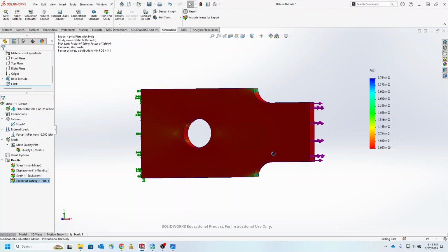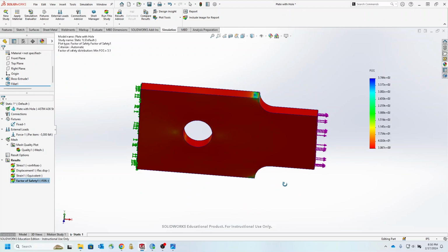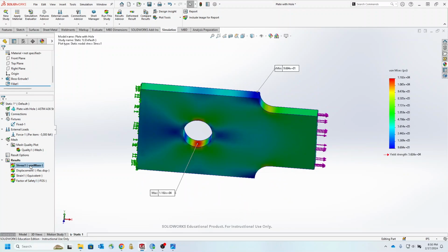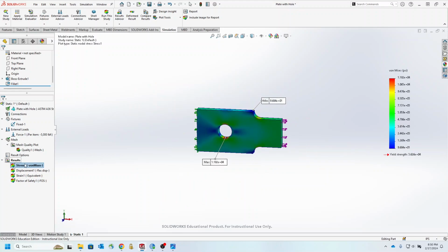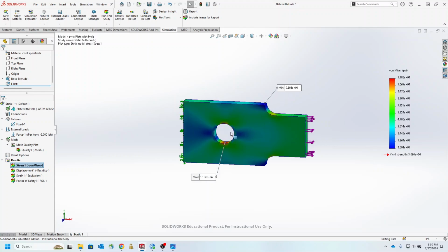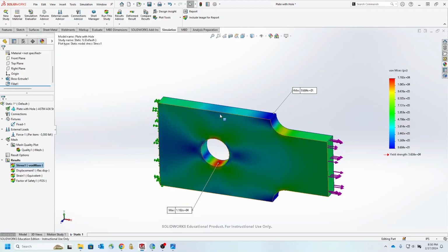So I would be in a safety margin of 3 times that stress. That might be beneficial, but essentially you will see that the first two plots are the ones you would always like to see, stress and displacement. Those are the big and major calculation results for the static analysis.